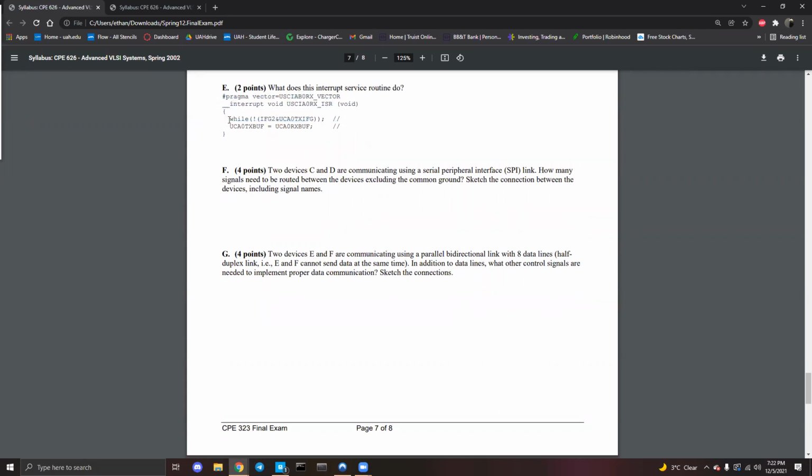This is just the ISR, and then this is the code, these 2 lines. So while not IFG2, it'll sit at this while loop until it receives an interrupt flag from the transmit buffer, therefore saying it's free, right? And then it'll write whatever it received, which got you in here in the first place. So this is already populated, right? It'll just send that into the transmit buffer, which is then, of course, sent out.